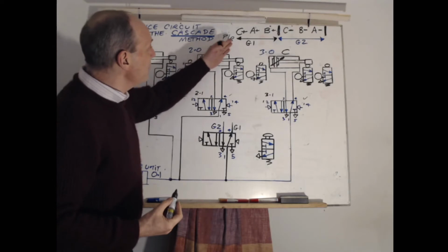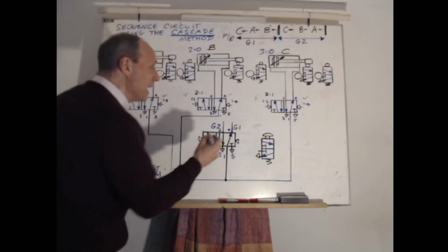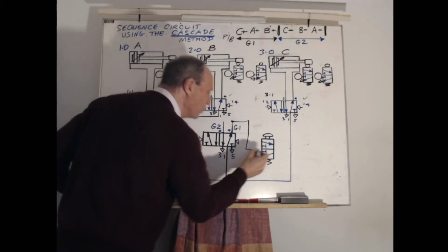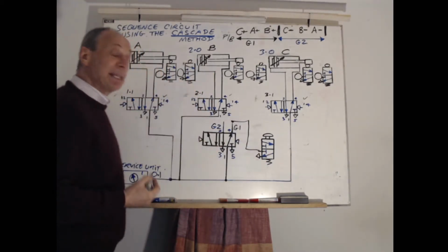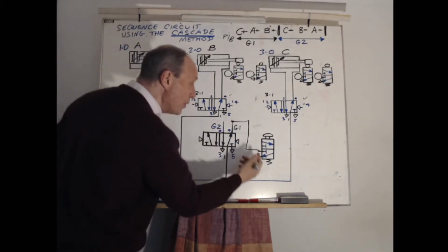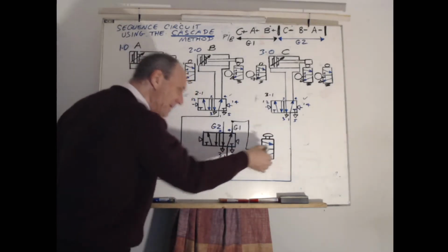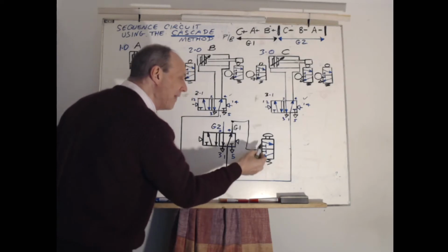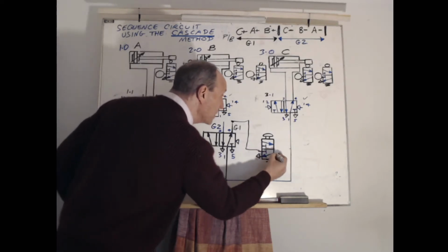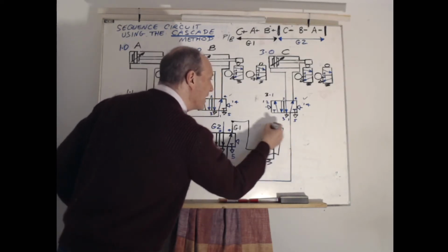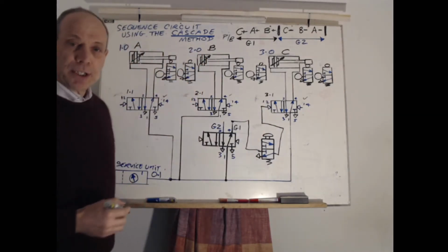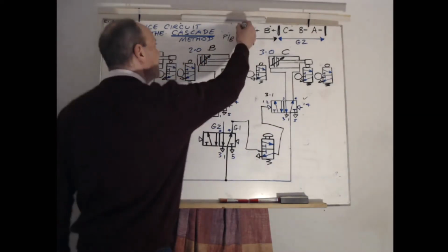So G1 is now going to start C+. So I'll take G1A and I'll feed it into the push button. When you press the push button, air will go through, and again imagine this top section comes down and this diagonal arrow replaces this stage, and therefore the air goes through, it goes out, and the first stage now is C goes into its positive forward stroke. So this has been achieved.